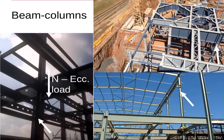And even, for instance, if you're having a look at these diagrams, here we've got a column, but the load being applied to it is eccentric, so that'll introduce a moment by its eccentricity. And then here on the right hand side we've got a column, and there's a crane that applies lateral loads and vertical loads at a distance. So that causes beam column behavior up at the top, and various other types of structures can experience both bending and compression.